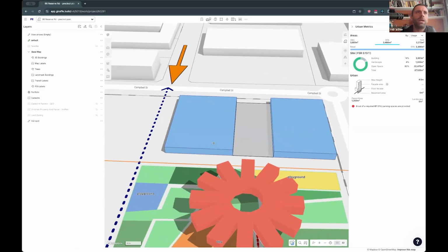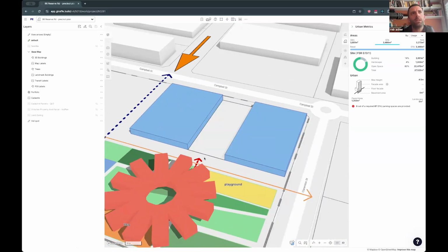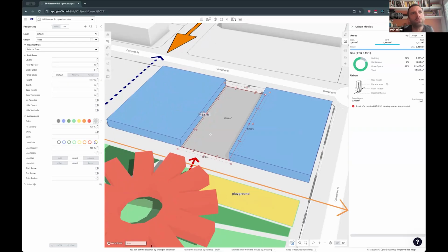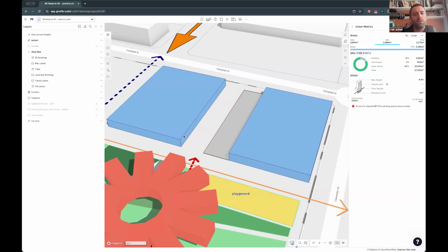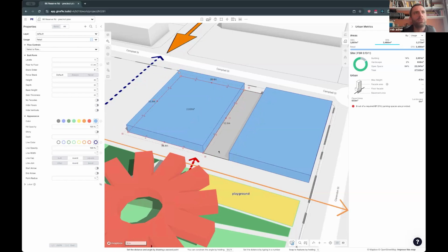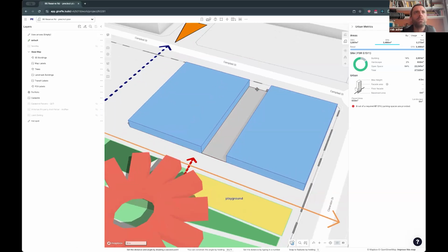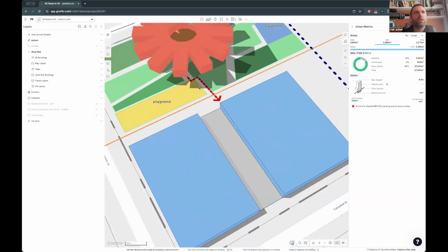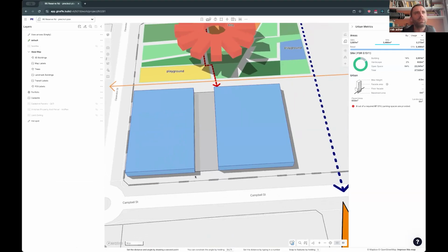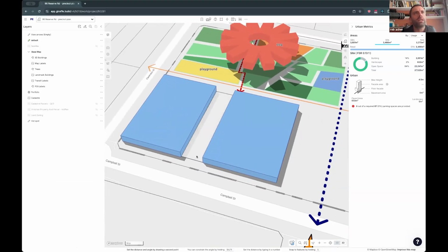But I kind of want to stay a bit in this. So let's say this is 22 meters, let's say our retail consultants come back and said it should be 12 meters. So I'm going to input the 12, then I'm going to hit the minus key, and that is going to give a relative offset. So I'm going to go 12 minus, and then I'll just hit B and snap this guy along. So now I have a precisely 12 meter, I guess, colonnade, plaza, whatever we're talking about, more of an arcade.